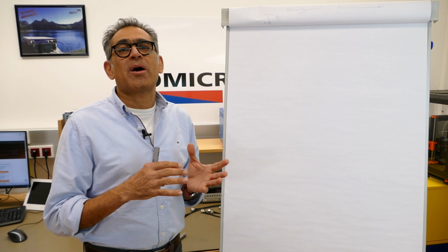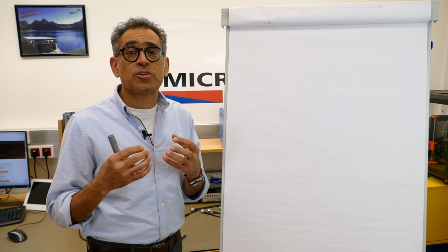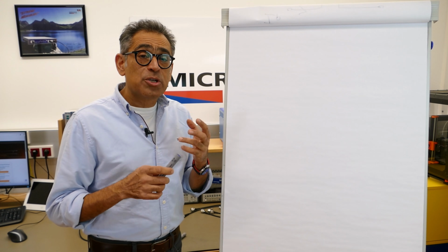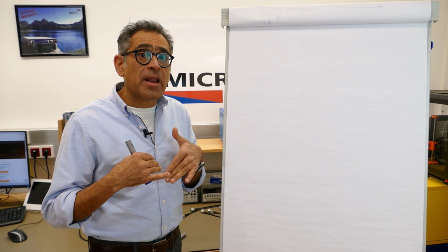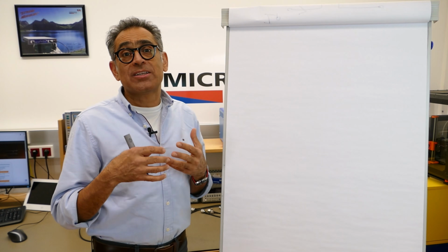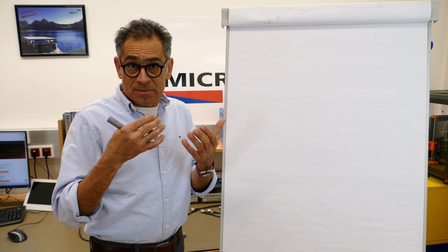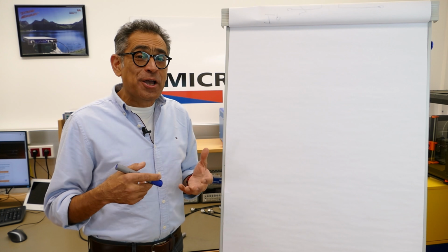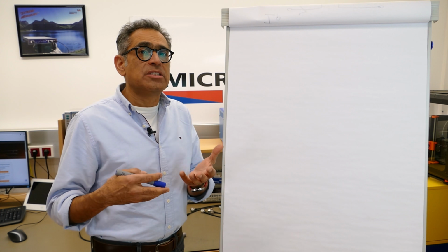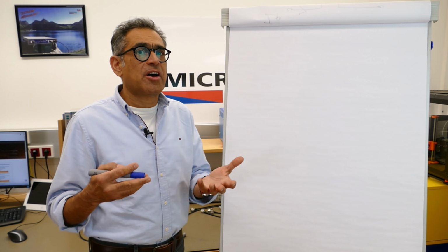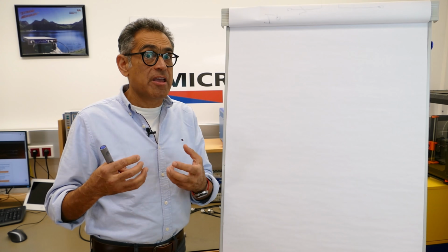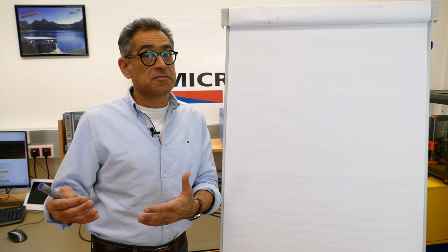If you remember from our previous videos, we talked about modes of noise coupling, in particular capacitive coupling and inductive coupling. And we showed that as the frequency went up, noise managed to couple quite well using these parasitic inductances and capacitances on our PCB. But a switch mode power supply is only switching at rates of a couple of 100 kilohertz. These modes of noise coupling were becoming very effective in orders of megahertz.